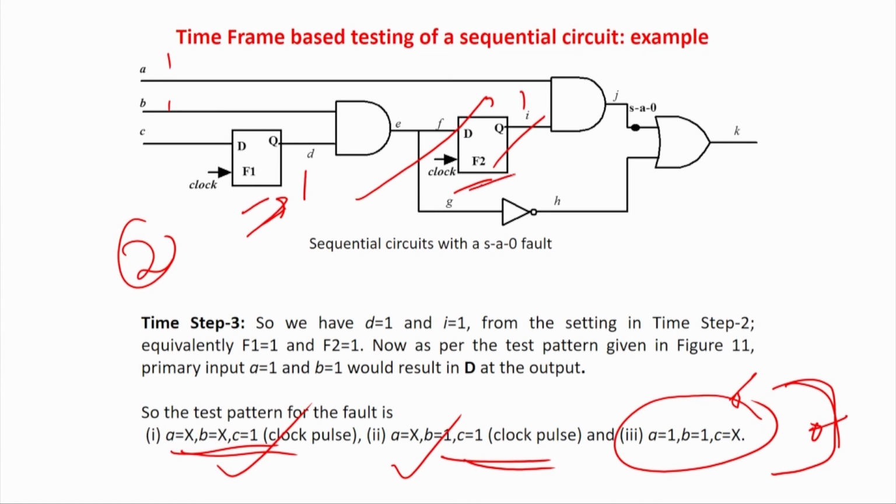So now the question is, if the test pattern application time is not saved by the flip-flops, then can we do something? Because scan chains are taking more area because of your flops. So what can I do? Some of the flip-flops I will make scan enabled, of course, which are very far down the depth in the line, because you will require a lot of ATPG computation to find out, as you have seen here, the level of this flip-flop depth is 2, so 2 extra test patterns were required.